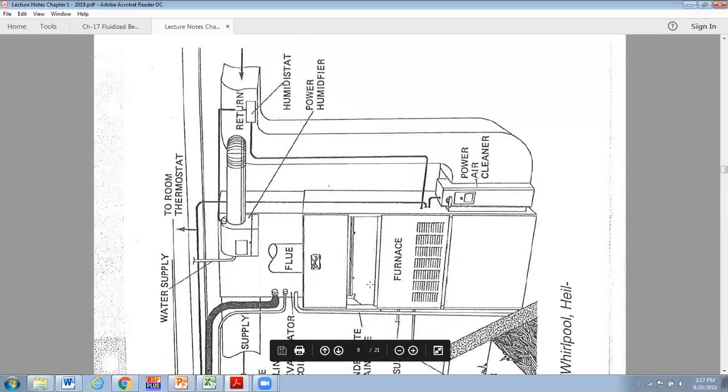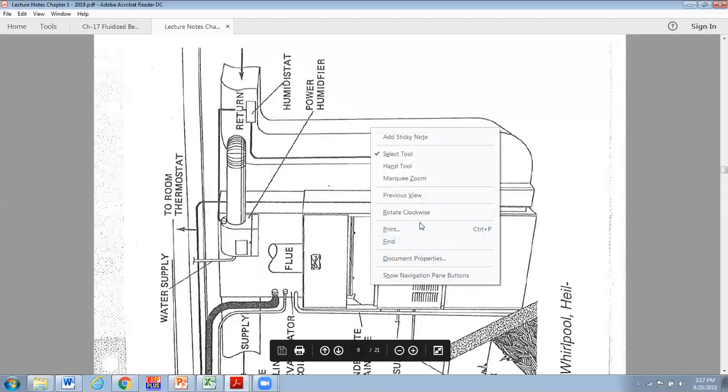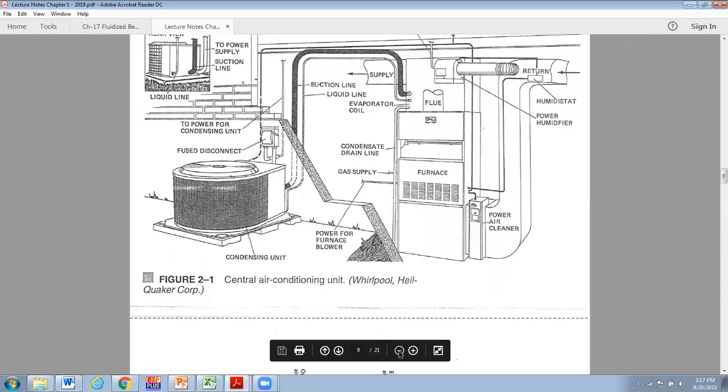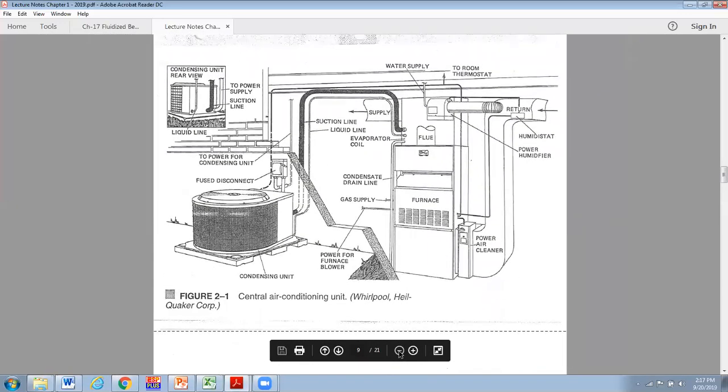Then we talked about the split system, which we usually think about as a DX type unit most of the time. Again, there are exceptions to just about everything, but by and large, the split has the condensing unit sitting outside that has the compressor, the condensing coil, and maybe some refrigerant receivers, and a fan.